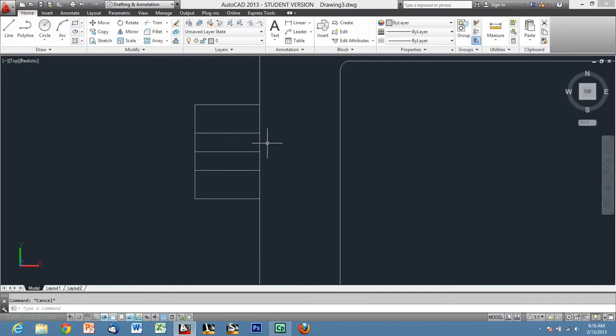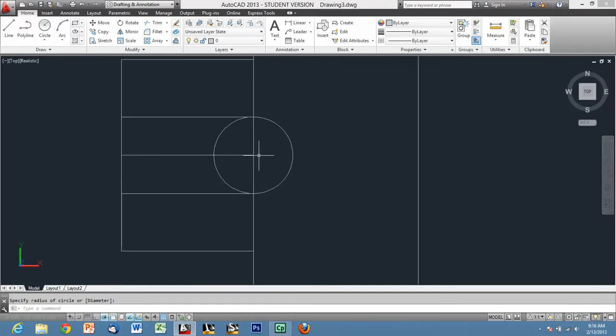And then finally I need to go in and build this circular shape here in the back. So I'm going to use my circle radius tool for that. And I'm just going to draw out a circle until it intersects with those lines. And then you'll want to make sure that the back edge is at the right location here. It should actually be a distance of 3 millimeters from here to here.